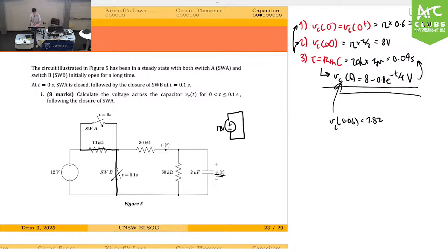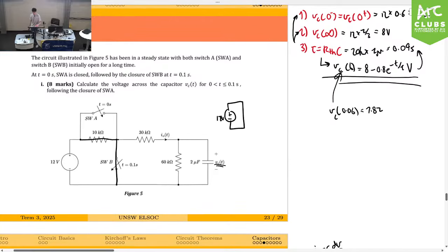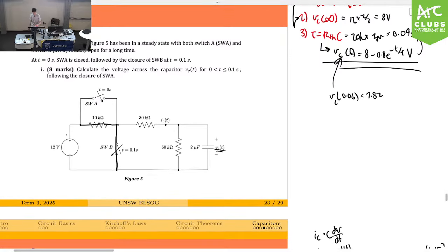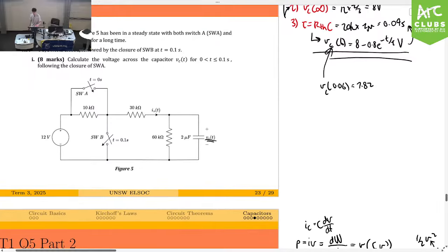You can't have 12 volts over a wire. I think in reality there's a bit of resistance inside the wire, something lab 1 or lab 2. But I think the maths works out for what we're trying to do, but just recognize it's a bad question. Okay, so if we short this, any current that we have through the left side of this circuit is just going to be going straight to ground if I set this to ground. So I've sort of decoupled my circuit. I've split it in half, in which case I don't have to care about the left-hand side. So really, I just have this.